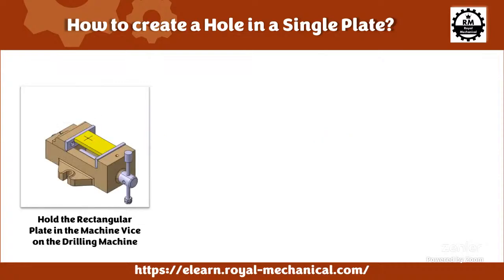And then we are going to take this raw material and hold it in a machine vise. This machine vise is present in the drilling machine. I'm sure all of you are aware of how a hole is made. Basically, a hole is made on a drilling machine using a drilling bit. To be very specific, these machines are called radial drilling machines, which are present in industries. And there is a machine vise present on this radial drilling machine.